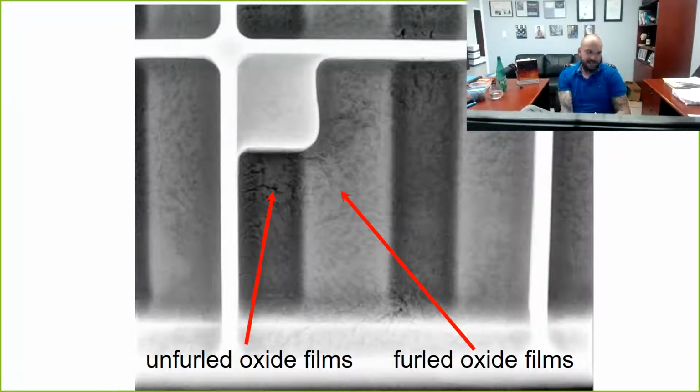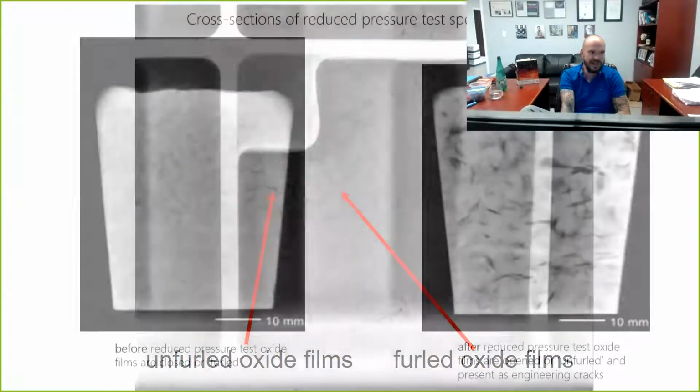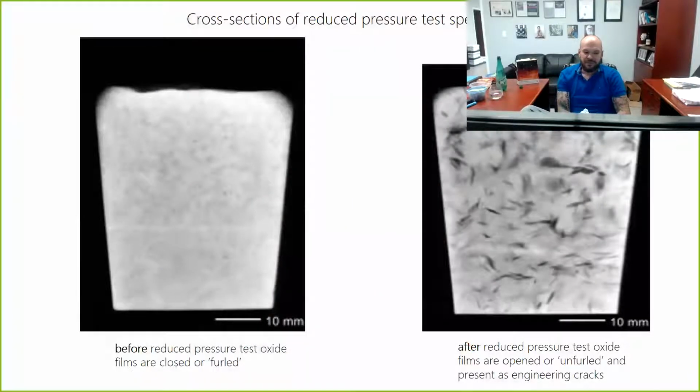Now this casting is a cooling stave for a nuclear reactor. I did the engineering on this. This is a nickel aluminum bronze 5 or 6 years ago. And these were the parts that were pulled out of the reactor. And so these were in there for about 30 years. So these are castings from the early 70s, right? And so the customer did not want castings that looked like this again. So we re-engineered with the proper filling system and produced castings that were absolutely perfect and completely free of those defects.